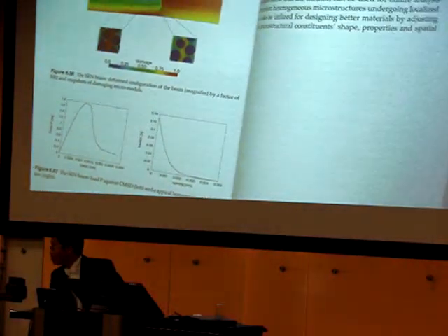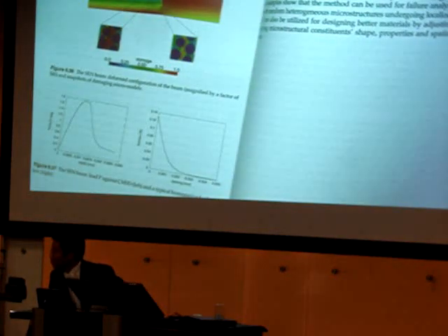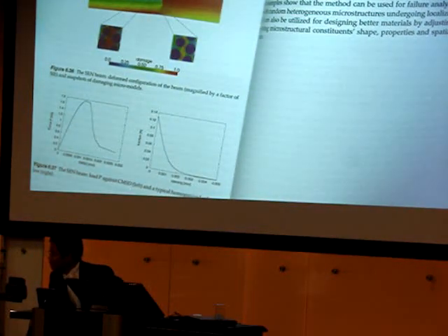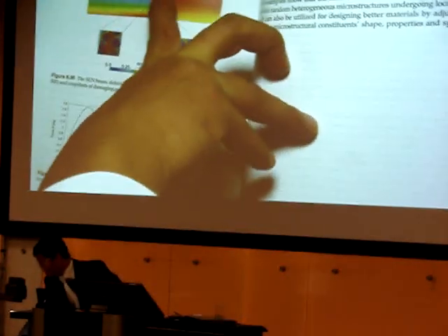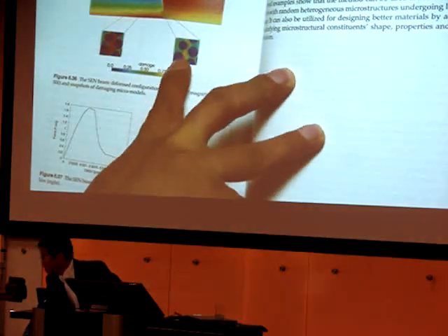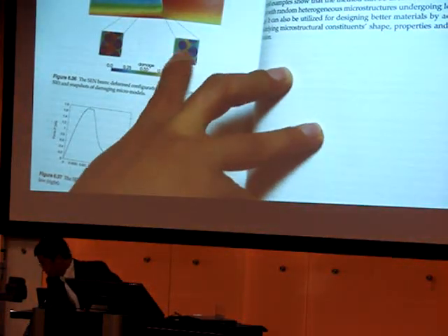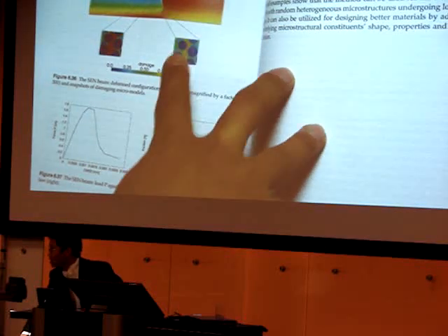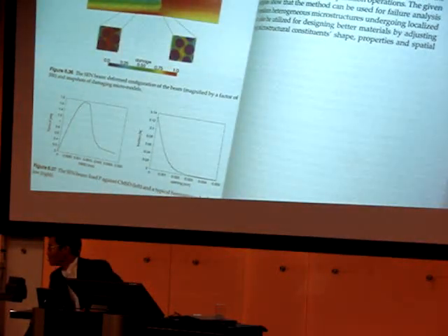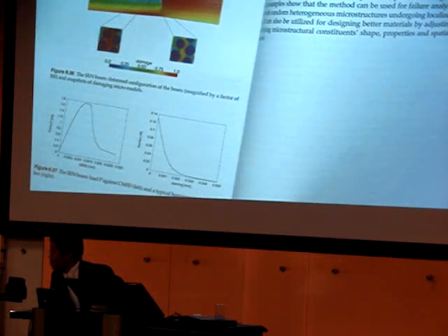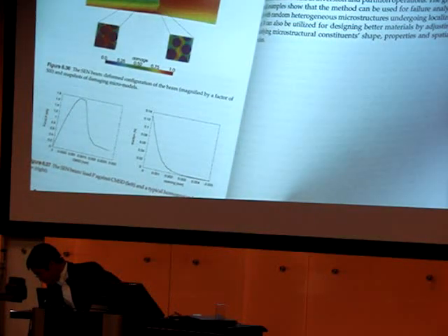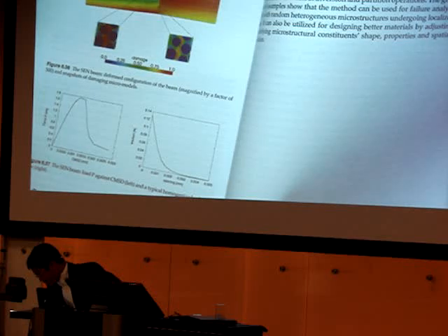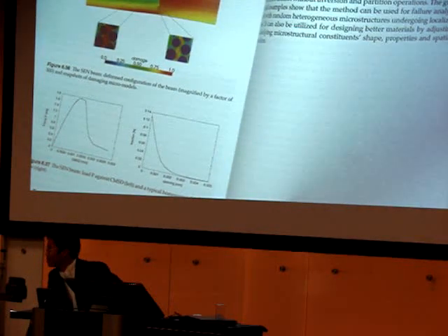This is happening because I used a quite large increment to reduce the cost. Because to every gauge point along this graph, you have associated RVEs, which are again discretized into, I think, thousands of elements. That's why. Okay, so these were very large steps. Yeah. How many steps was such a total curve to compute? Maybe, I think, thirty something.